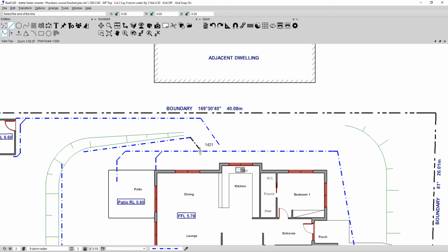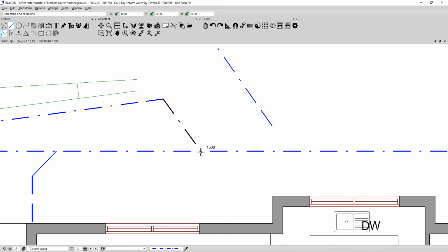Now again, I don't want it to see the diamond here. I don't want it to snap to that because otherwise it'll jump to be right angles. So I hold down the control key and click. Whoops, I'm in the wrong spot. I'm going to go Control Z, which undoes where I'm at. I could have used the undo button, but Control Z does exactly the same, and so does Command Z on a Mac machine.